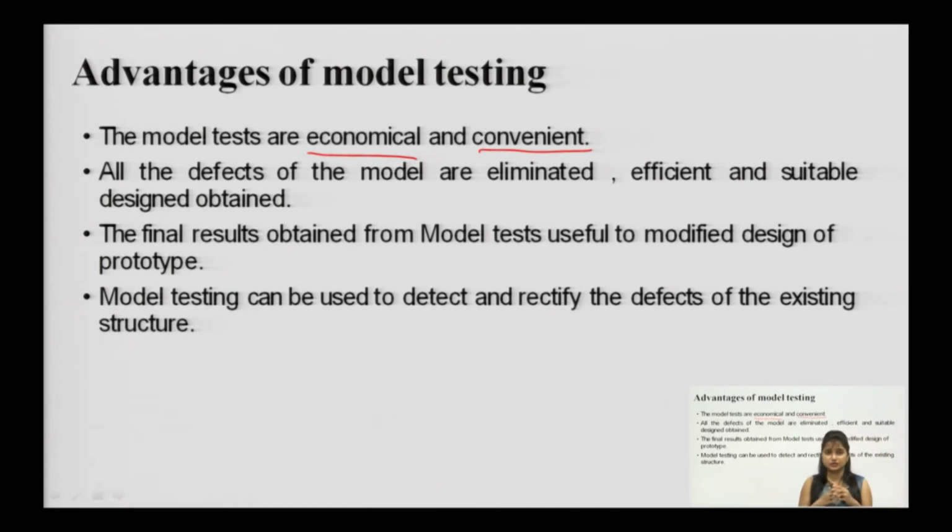Like if you have some structure that is not in a very good condition, for example a lane, where the day to day traffic load is increasing and the structure is very old, and it was not designed keeping in mind that amount of traffic. So, what you can do is take the dimensions and prepare a model of it, then put the corresponding loading on it, and hence you can determine whether the traffic can be reduced, whether it can be widened, whether it can be taken into another lane, or whether it can be provided extra support from the bottom. This is what is meant by detecting or rectifying the defects of existing structures.